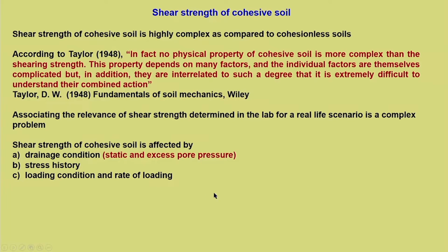Loading condition and rate of loading, well, that does not need any explanation. Initial condition, initial compaction state, for example, what is the water content or the dry unit weight, specifically in case of remolded samples.